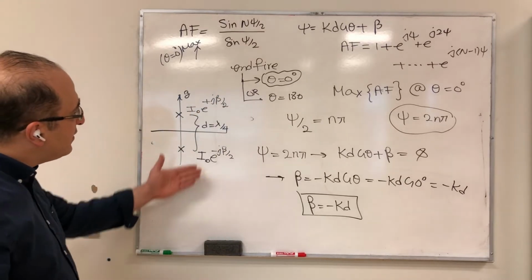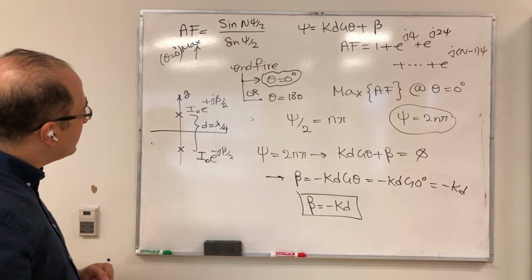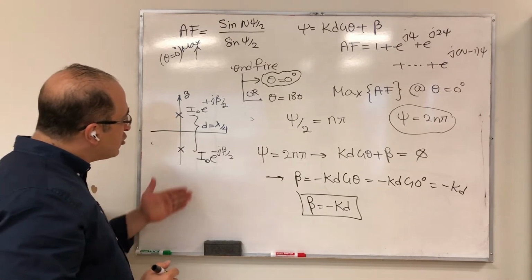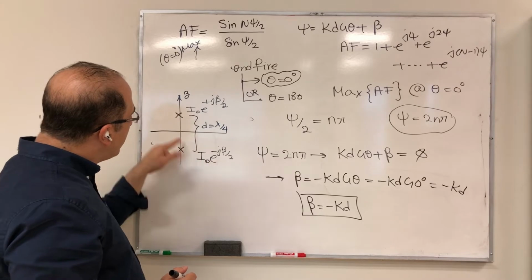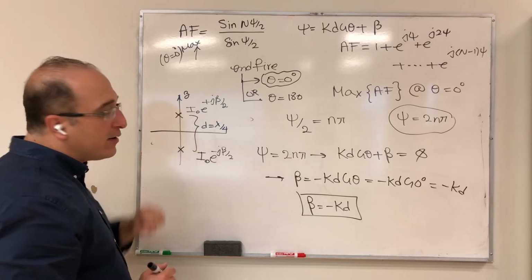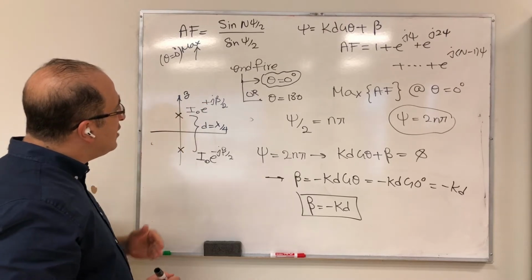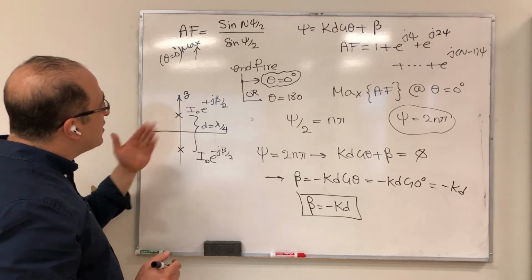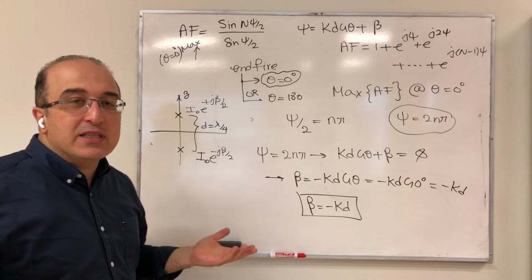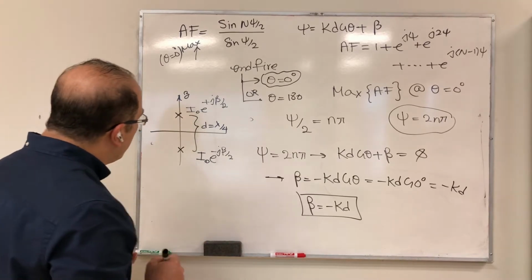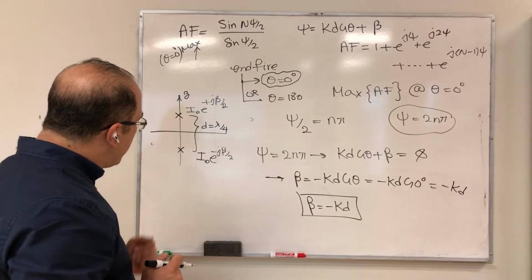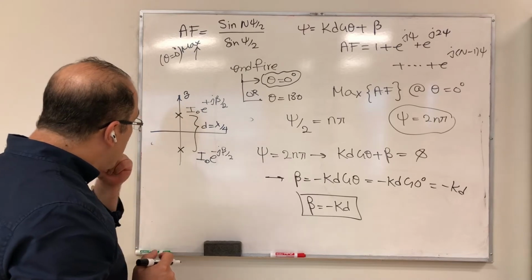I mean, the reason I did that, the way that I did that, is to ensure that I have my phase center at the center of the array. I could have just said I naught and I naught to the power of j beta, but I wanted to have phase of 0 here. So this is essentially up to you. So if that's the case, this is my antenna array that I have right now.